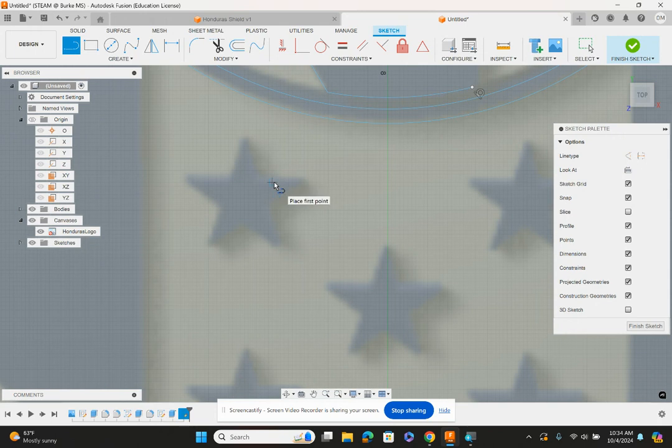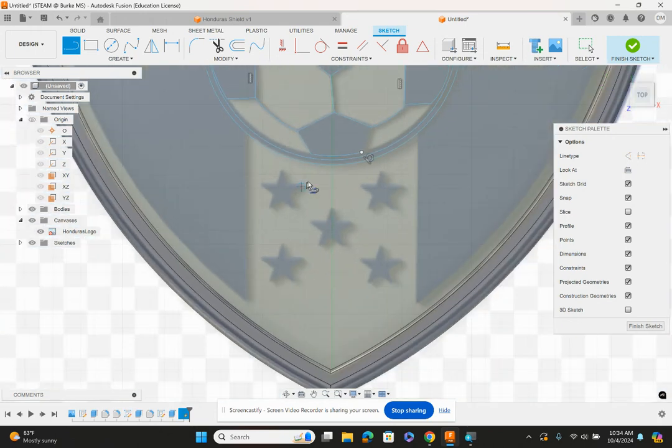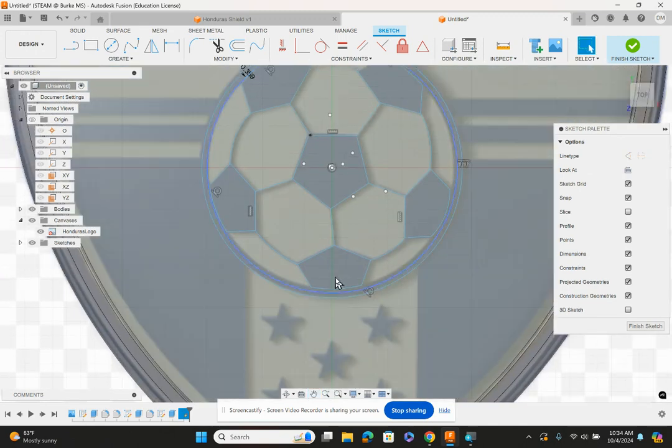Okay, so I'm back. So I did a lot of it here. I think I didn't close this line here. So it's very important that you close everything. So everything is now clickable. If you click select and you look in here, everything is enclosed. So I used a lot of arcs and lines with this, and just make sure everything is enclosed.